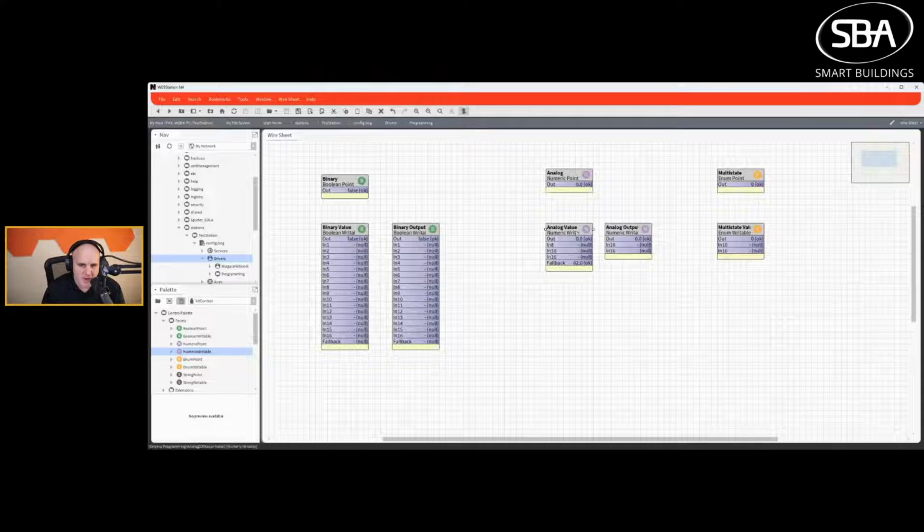We'll get an online one for our next one so that it'll work, because it's offline, it's not going to work because I'm just working on a database and I'm not working on anything actually live storing data. But that's what would happen essentially if I wrote to input 16 with 62 or with 0, I would then get 0. If I wrote to 8 with 70, I would then get 70. And if I deleted all those to null, I would fall back to 62. That's how the priority array works.